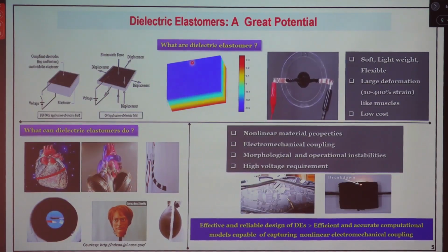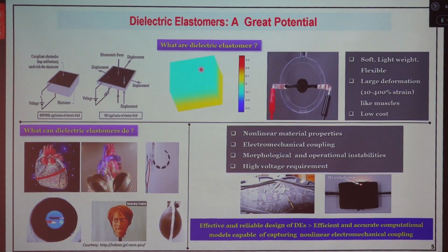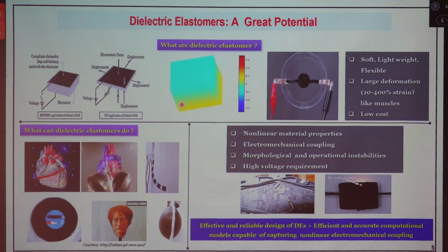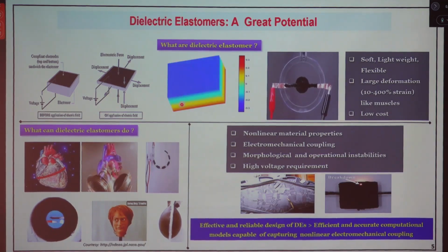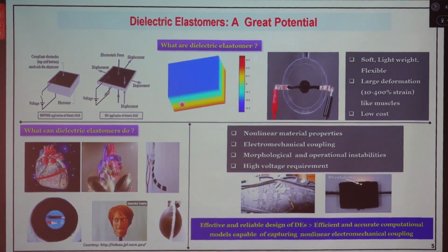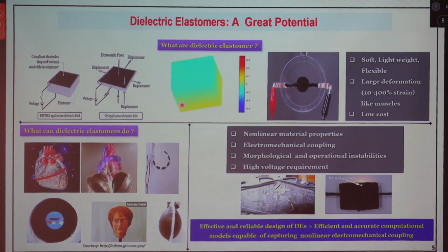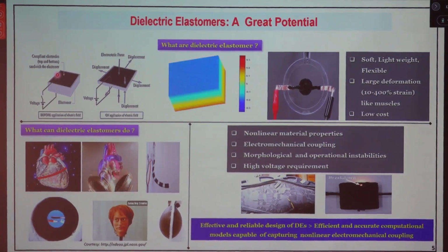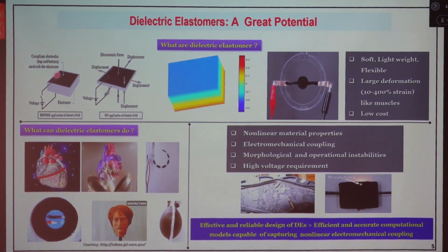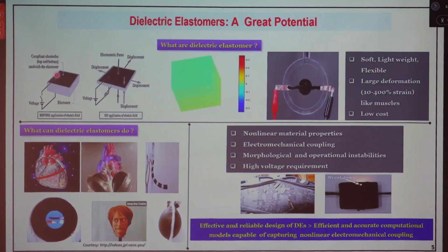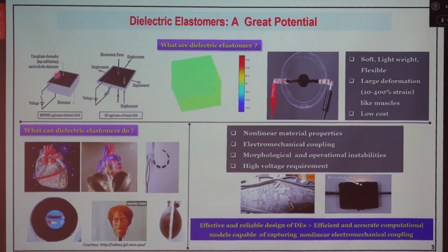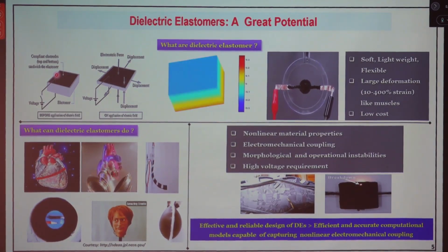I hope you understand. With the simulation you can understand it better. There is a cube of the dielectric elastomer. When the potential difference is applied, it compresses in the thickness direction and expands in the areal direction. We have already seen that the dielectric elastomer, or elastomer materials, are incompressible in nature, so the volume that is there initially remains constant. I hope you understand the basic mechanism. What is a dielectric elastomer? It follows a simple principle: when the potential difference is applied, because of the accumulation of charge, the membrane compresses in the thickness direction and expands in the areal direction.